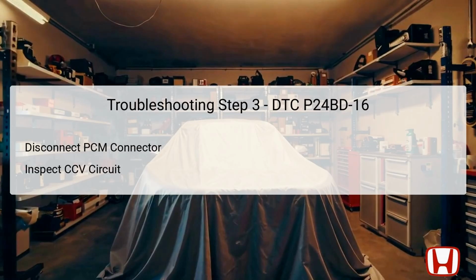Once the PCM is disconnected, inspect the CCV open wire condition to determine if it meets the threshold of less than 1 ohm for continuity, which indicates a properly functioning wire. Following this, check whether the CCV is shorted to ground, ensuring it exceeds 1 megaohm. Any abnormalities at this stage signal a potential fault in the wiring or CCV that needs addressing.